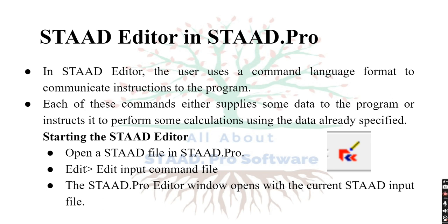How to open a STAAD editor file. Open a STAAD file in STAAD Pro software. Normally, what we do in STAAD Pro software, we will do for this also, that is opening a new file. Then in the ribbon tab, we can see the edit option. From that, select edit input command file.